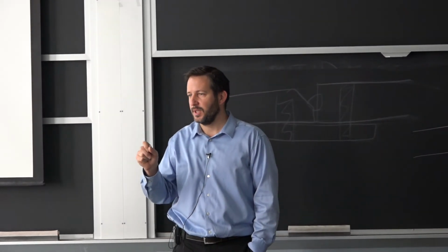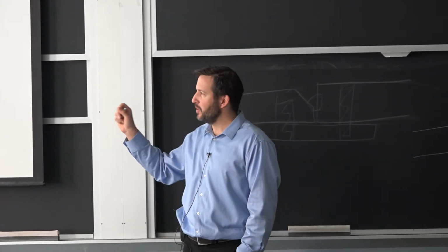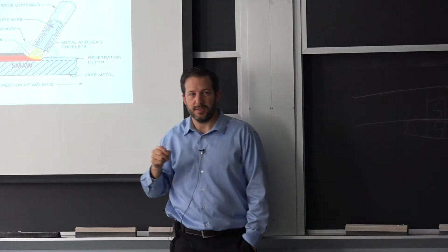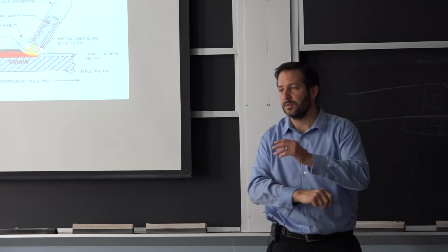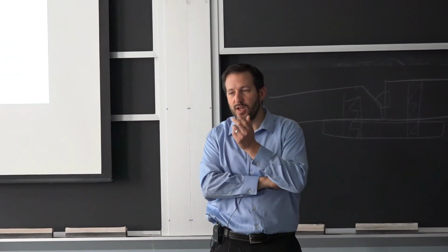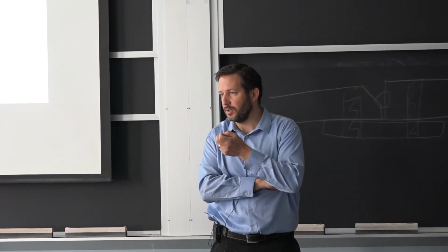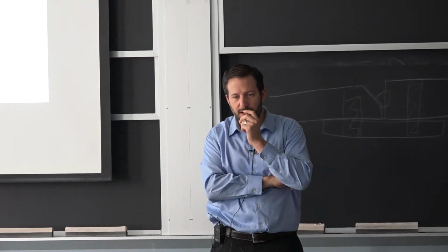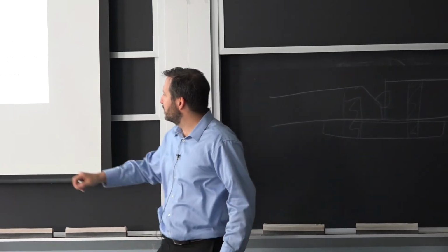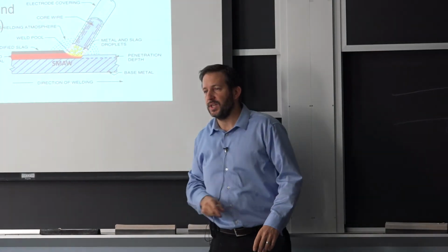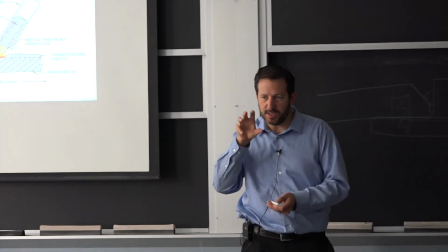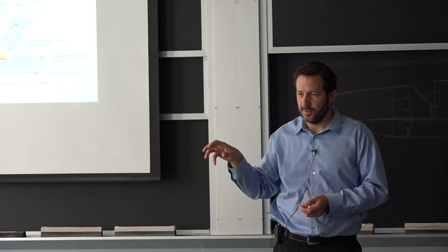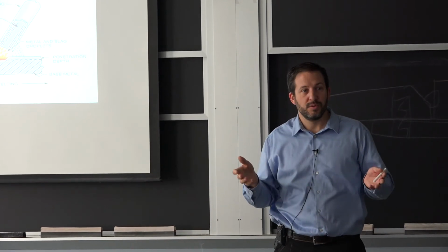And a lot of times there's going to be a little bit more money spent in the metal that you bring in to weld than the big piece that you're welding. So you're able to make this weld metal a relatively good quality. And a lot of time you end up worrying about what you did to that base material more than anything else, because you come and you heat up this zone, and then when the arc goes away, it cools very, very quickly.